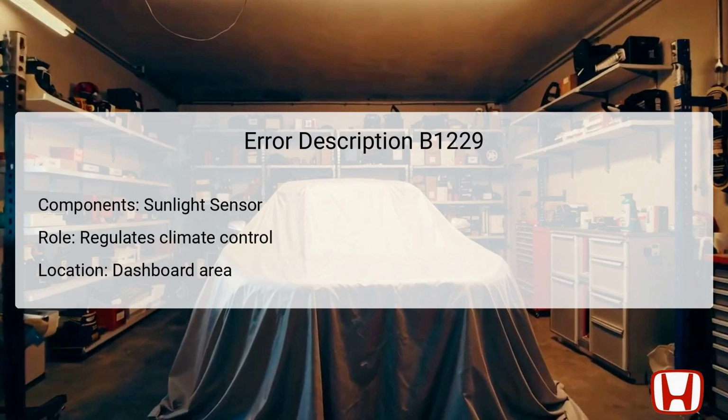DTC B1229 indicates an issue with the sunlight sensor circuit, specifically relating to the sunlight sensor located in the dashboard area of the Honda Odyssey. The sunlight sensor functions by detecting the amount of sunlight entering the vehicle and communicates with the climate control unit to adjust the air conditioning accordingly. This adjustment is essential for maintaining a comfortable environment inside the vehicle.